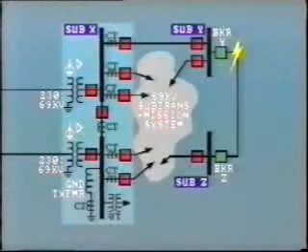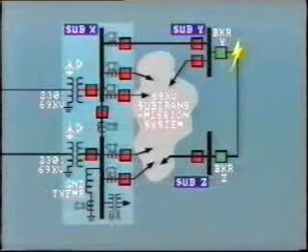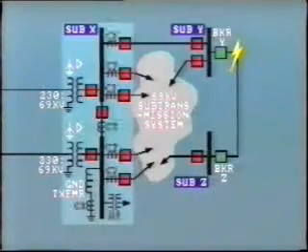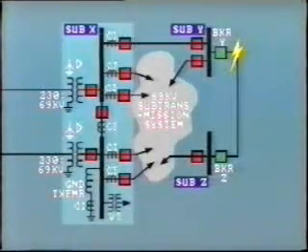This example has demonstrated 2 things. First, the nature of a fault can change during a disturbance, and in this case, the protection operated correctly to clear the fault. Secondly, our examples showed that recording equipment located several buses away from the actual fault can still provide valuable information during a fault investigation. Let's now move on to our third case, an overtrip for a remote fault. This is a clear example of misoperation.